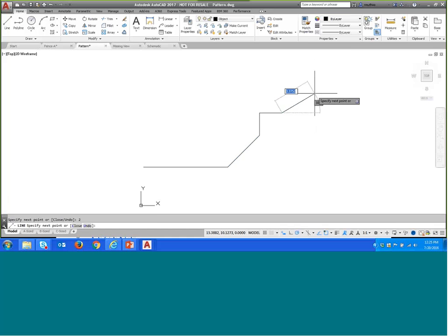Now it's possible, but going and finding that 35-degree angle is really hard. The actual use of drawing aids like object snaps or polar snap tracking is the ease and speed, to speed up your drawing capabilities. If you have to actually go and find these angles, it doesn't make sense. So we have to set it, and while we are in the command, we can set a new angle.